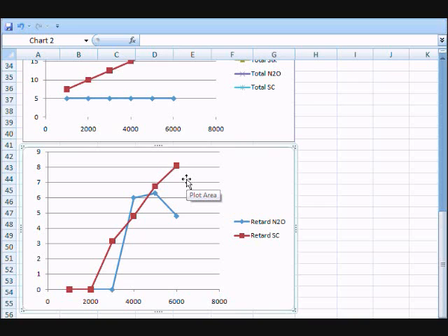I mean, the numbers aren't exact because timing numbers differ from one engine to another, from one octane level to another, from one compression ratio to another. But what's important here is the trend. Is it increasing? Is it flat? Does it dip at any point? And where your minimum and maximum points are, because that'll help you tune your setup faster.